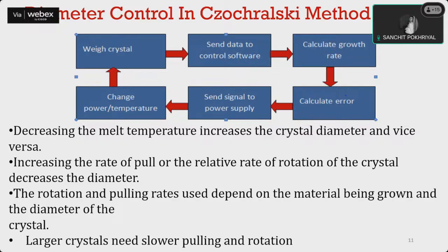So we are not at the thermodynamic equilibrium, right? We have read that a crystal cannot grow at thermodynamic equilibrium. So it is near the thermodynamic equilibrium. So near the melting point is near the equilibrium point as well. Yes, at the melting point, it is equilibrium. So what happens if your seed is touching the melt at the melting point, with both at the melting point? There will not be any crystal growth. For crystal growth, the seed has to be at a lower temperature, and the melt has to be at a slightly higher temperature. Okay.